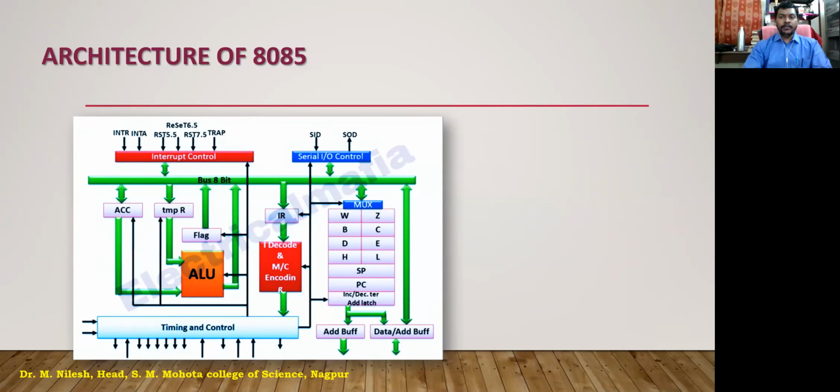So whenever we are executing instructions which have memory as one of the storage locations, it implies indirectly that the address of that data should be in the HL pair. I hope you got this. So the HL pair stores the address of the data. It specifically stores the address of the memory location where the data is being stored.